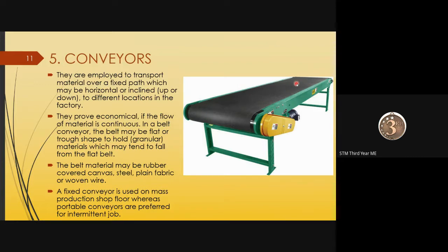With too much stretching, tension may occur and it may break. Also, it may not provide sufficient pull. There will be sagging, and obviously the friction generated at these two points will be less. So the belt will not rotate as per the rotation of the roller. So you can't bring it to that much length.